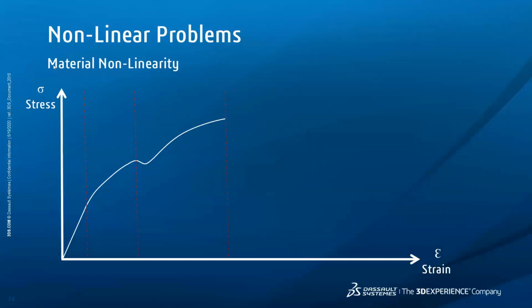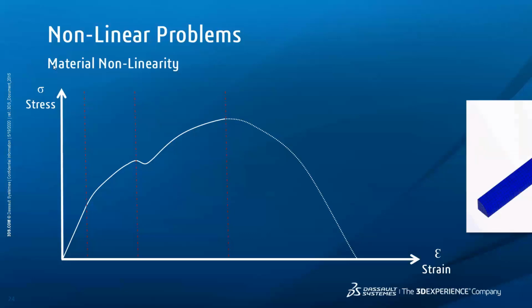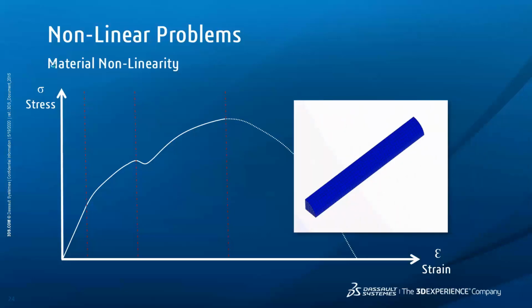As we move beyond the material's maximum strength, we will see a loss in stiffness. As such, we could simply use a failure measure and stop here. However, with SIMULIAworks, we can go further. We can define whether and when damaging behaviour initiates and how it evolves during our analysis. There are a number of options available for this.